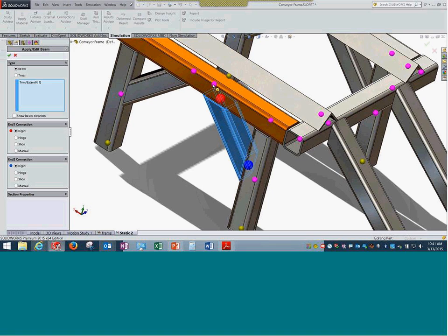It is a hinge wherein only the translational degrees of freedom are transferred, or it will be a slide condition, wherein rotational degrees of freedom are transferred but the joint can actually slide. So those manipulations can be done. I have rarely seen users comfortable using it, but the option is present in the software. You can also treat all these beams as elements. These are more stiff elements, without bending in them. They just transfer linear forces.